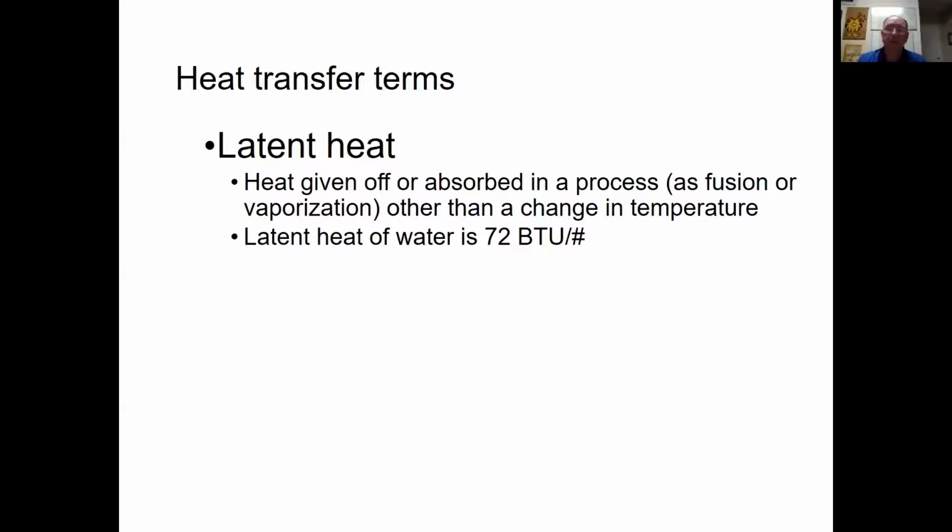You don't hear us talk about that very often because we've already taken that latent heat value, if you will, into consideration when we're trying to figure out what your heat transfer needs are. So if we tell you you need 3 tons of cooling, then we've taken into account that that latent heat has already been calculated into that material.